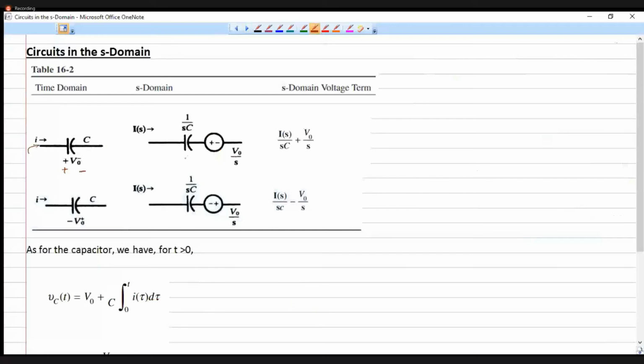Okay. Now it is modeled like we are having a capacitor already, and in order to represent this, we have to use integral IC of t dt. Okay, where I have a current that is flowing through the capacitor. Plus, there is one initial voltage that is available with polarity like this. Okay, now we are traversing from left to right. So we are encountering the polarity from plus to minus. So this voltage is in additive manner. So that should be taken as equal to plus V naught.